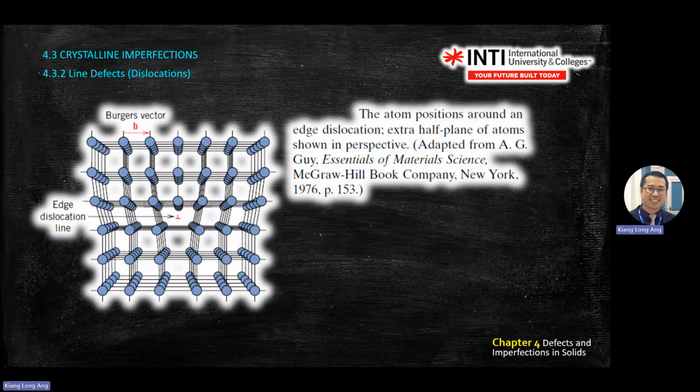Okay, this one. When you observe, you know that this one got a missing line of atoms. So there's an inverted T here. The action stops here. When there's a force from this side, you press this side, right? So this one doesn't have anything, it still continues to push. But when the force pushes this side, there's more room for it over here that allows this one to push further.